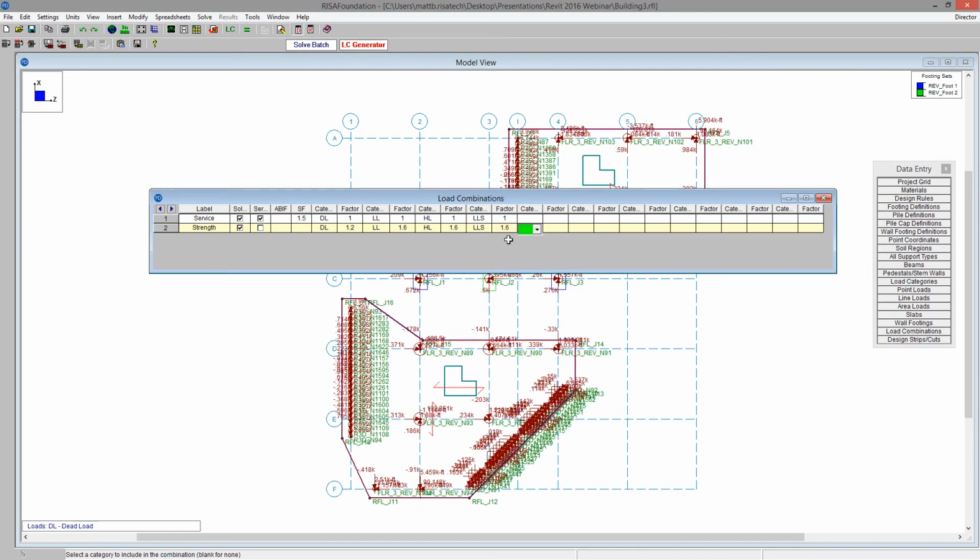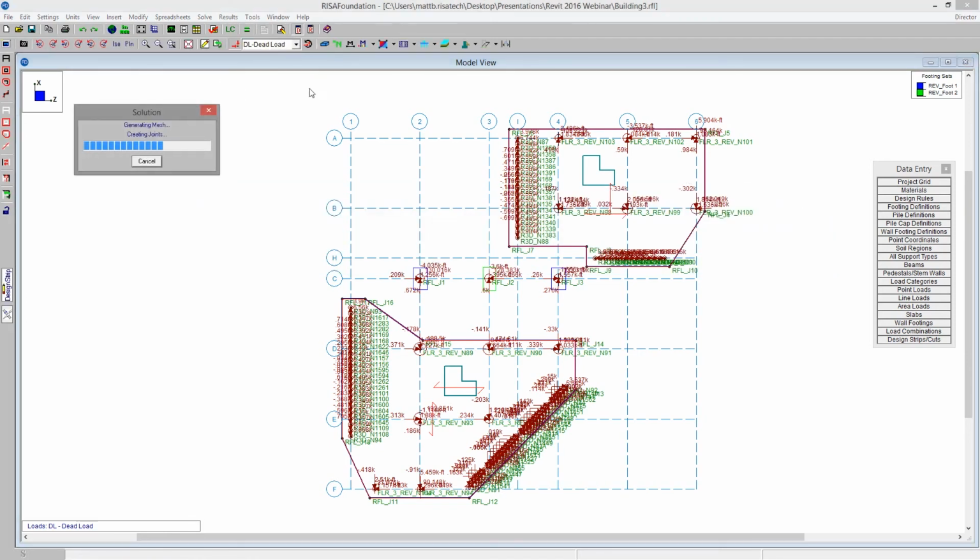Of course, just like in RISA Floor and RISA 3D, where I mentioned earlier, it's best to generate your own load combinations. I would always recommend doing that in RISA Foundation as well, because the two default load combinations may not capture all the categories that you need. So of course RISA can't determine everything for you automatically. It's always important to review all that input, especially things like load combinations, very carefully and put your engineering judgment onto that, because the last thing that we want in this situation is a garbage in, garbage out scenario where we ignored a certain load combination because we thought the program had automatically done that for us.